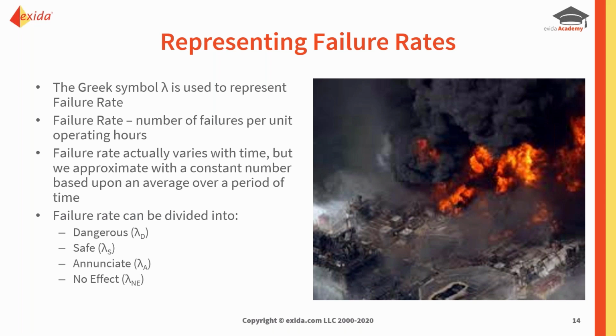But we also need to know the safe failures, because we will have some spurious trip target to meet. Spurious trips are trips that occur unwanted, unexpected. They don't cause a problem other than the fact that they trip. And of course, we know that in some applications, if we have to restart after a trip, that can, number one, be costly, but number two, can also involve quite high risk. So clearly we don't want to be having what we call spurious trips, unwanted trips.